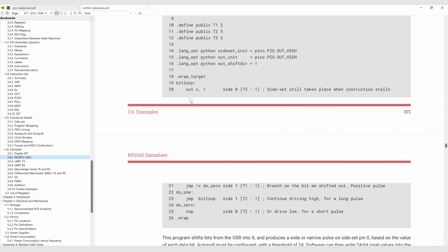What makes this confusing, and cool about the PIO, is that every PIO instruction can have a delay associated with it. If you've ever done bit banging in a microprocessor, it's all about setting an IO and then creating a delay, setting an IO, creating a delay. But the genius behind the PIO is you can do them both with 1 instruction. So that's why 32 instructions doesn't sound like a lot, but you really can do a lot with them.